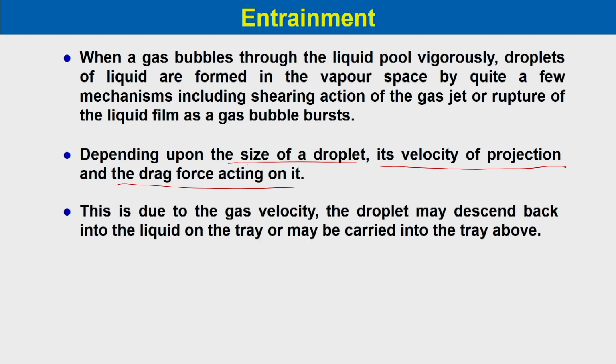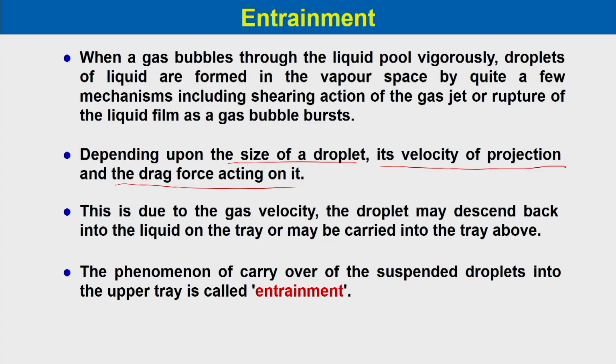Due to the gas velocity, the droplet may descend back into the liquid on the tray or may be carried into the tray above. That is why, when there is a very high gas velocity, entrainment occurs. The phenomenon of carryover of suspended droplets into the upper tray is called entrainment.